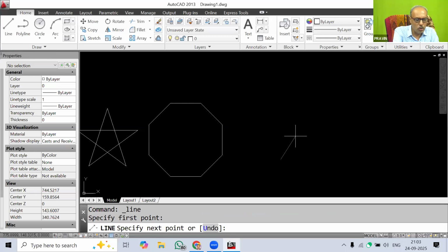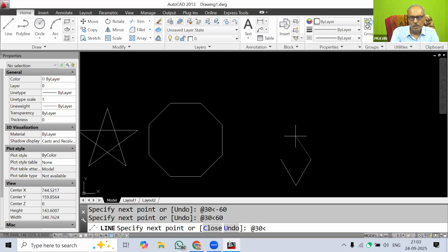So I will go @30<-60. Then @30<60. Then @30<0. Then @30<60. So it was wrong, so we will type undo.